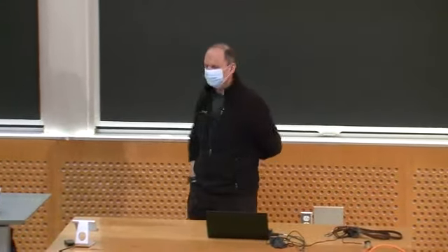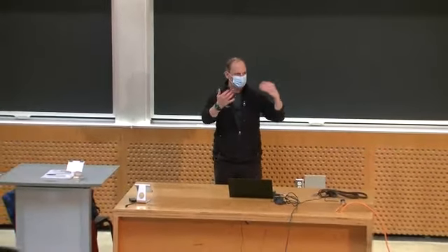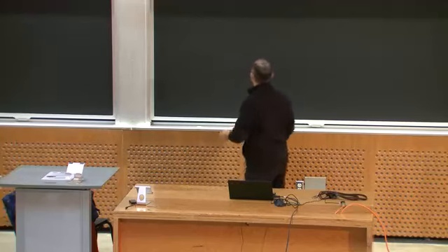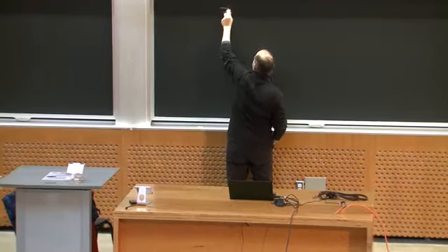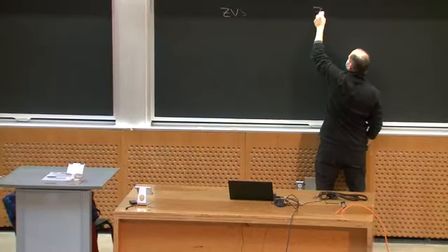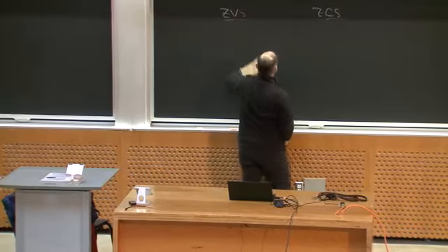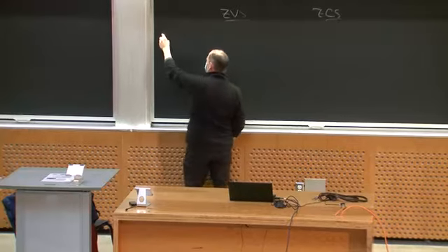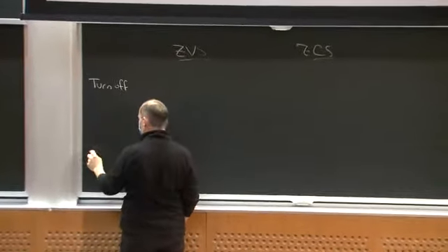I'd like to continue our discussion of soft-switched power converters today. If you'll recall, when we think of soft switching, we're thinking of the switching transitions when we're commutating between devices. I can consider zero voltage switching, ZVS, and zero current switching, ZCS. Some switching transitions can give a combination of both, depending upon the design. But we also have to think about switch turn off and switch turn on.